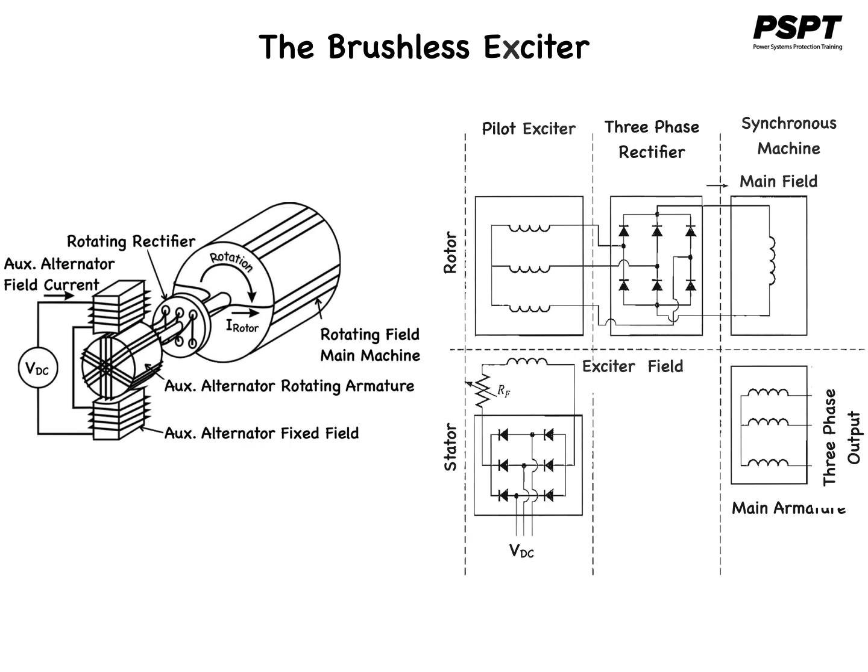By controlling the small DC field current of the exciter generator located on the stator, it is possible to adjust the field current on the main machine without slip rings or brushes. Since no mechanical contacts ever occur between the rotor and the stator, a brushless exciter requires much less maintenance than slip rings and brushes. To make the excitation of a generator completely independent of any external power sources, a small pilot exciter is often included in the system.